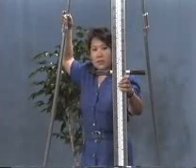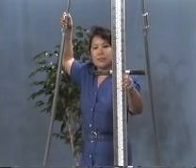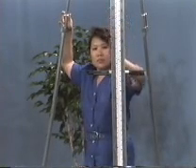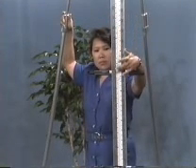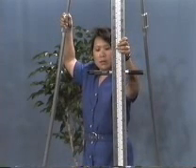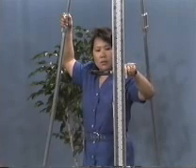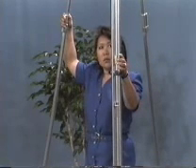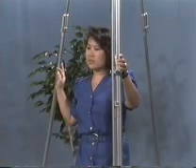This is a first order leveling rod, also known as an Invar leveling rod and meter rod. This one is aluminum with an Invar tape with graduation marks in meters. Invar is a metal alloy that resists expansion and contraction due to temperature fluctuations. Springs are attached to maintain a constant tension and stability. The rod has a hard metal foot and sets up on a heavy metal boot.